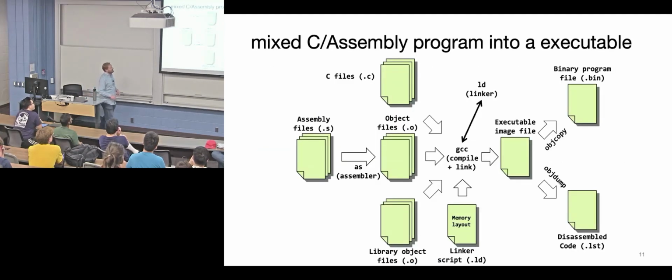Okay. The last thing to think about with a tool chain is you have some C files. You may have a library that you're compiling. You might have some precompiled assembly files. Your assembler is going to turn those, and your compiler is going to turn those, into object files. You're going to have some other libraries. And then your compiler GCC linker is going to take all those things and put them together. And as we'll see, remember, in your C files, you're going to have variable names. Well, you don't know where that data is in memory. Well, the compiler here and the memory layout, we call the mapper, come together and resolve all those links